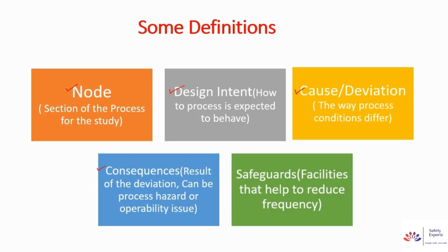So these consequences we are talking about in the purview of Hazop study only. In other hazard identification techniques, the operability issue is sometimes not considered, but for the hazard, it is considered. Now the consequence can be financial, a safety risk, loss of reputation, or environmental consequences.